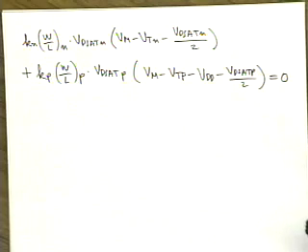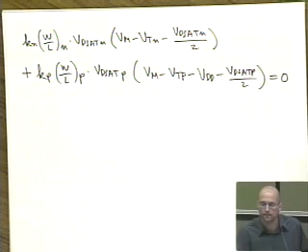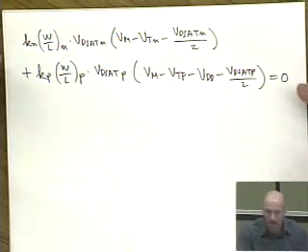Question? You assume that VD sat is less than Vm minus V threshold. Is that true for the PMOS? Using the parameters that you gave us on page 103, they don't seem to be right. That's an excellent observation. You make an assumption, carry it through, and then go back and check your assumption. In this case, PMOS will be in saturation and NMOS will be velocity saturated, if you want to do it precisely. But it's an excellent point.